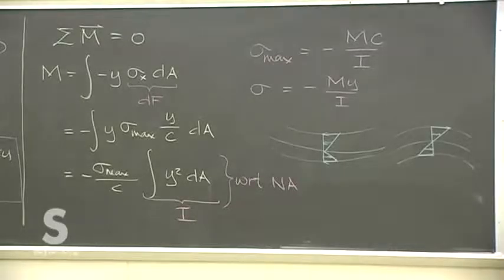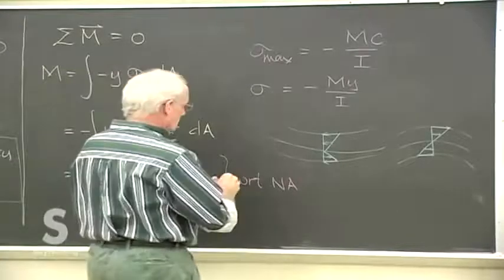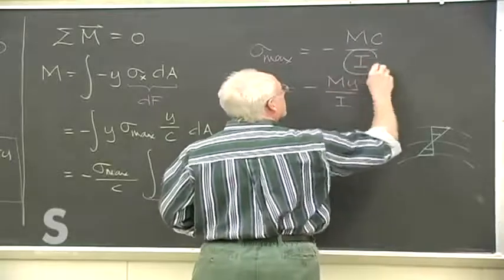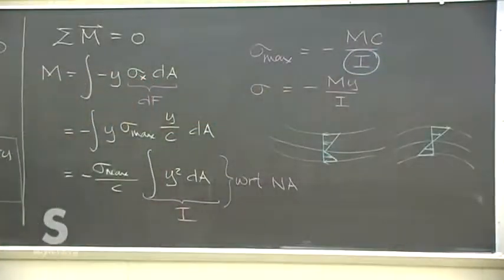But the biggest revelation with this is that the smaller the moment of inertia, the greater the normal stresses. As I goes down, the stresses go up and vice versa.